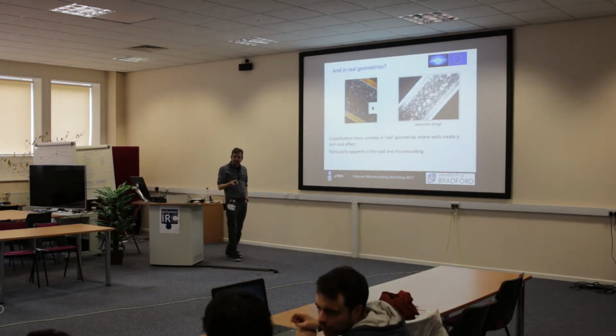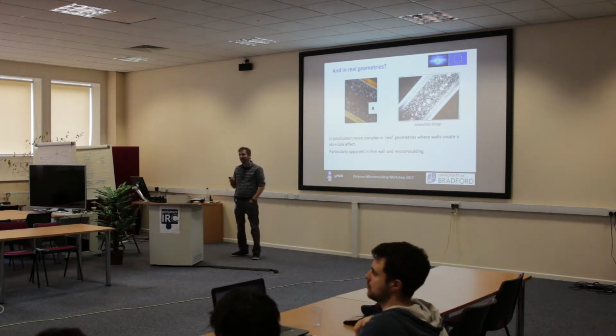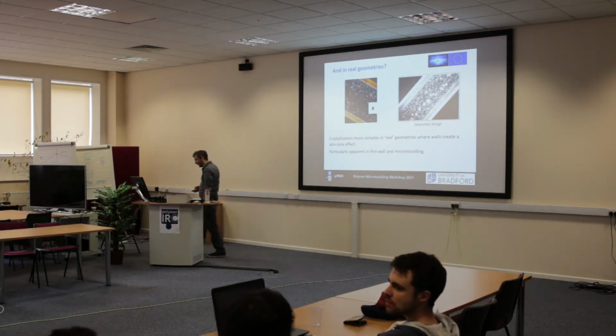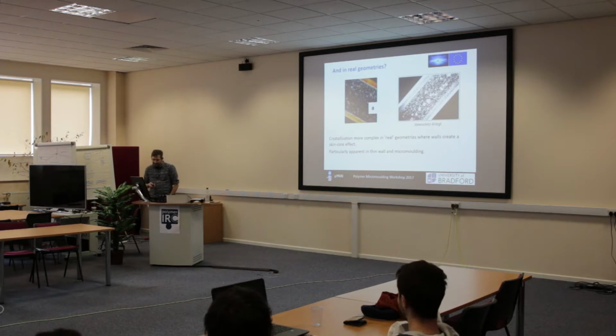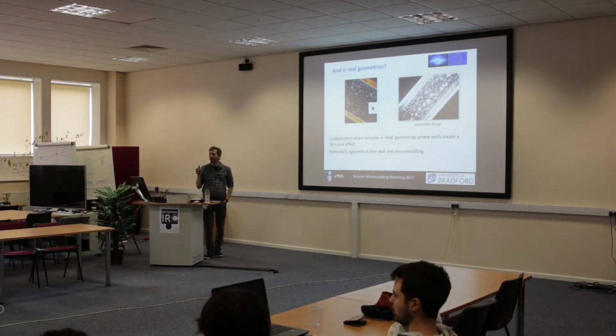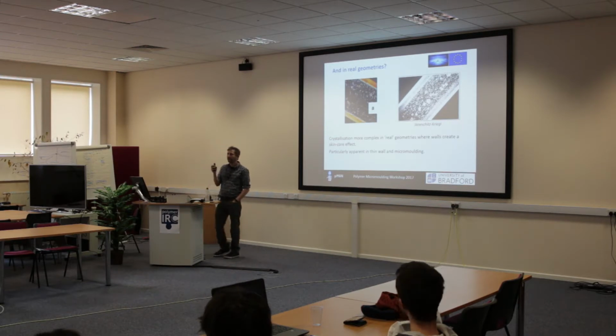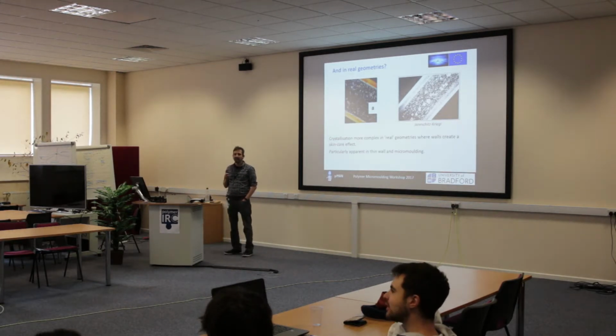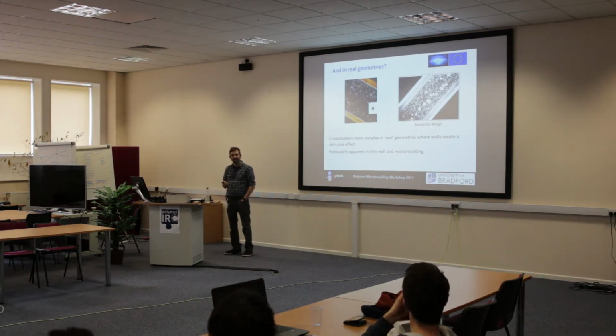Now, in moulding, you've got lots of things going on, okay? If you look at your micromoulding process, all your temperature is controlled at the wall, okay? There's nothing controlling the air gap in the middle, okay? So you can see that the thermodynamics of what happens in the center of a mold compared to the thermodynamics of what happens at the wall of the mold are entirely different.